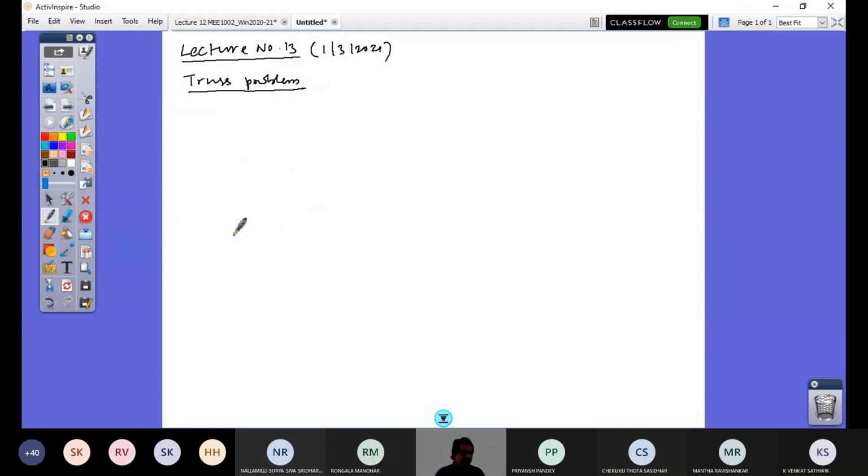So let me just explain this truss. Look at this truss. As I have told, a truss has to be formed by arranging slender members in a triangular fashion. So I have this arrangement, and I'm going to sequentially add to it so that I can develop my truss. I'm going to add members like this. See, now again I have formed another triangle. So this is going to be a truss. Again I'm going to add another member like this, and that's going to form a triangle. So again this confirms the structure's nature, right?